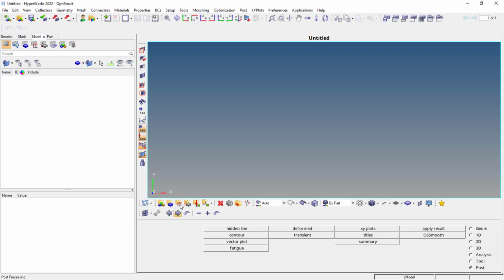Once you are done with the components, we apply the materials. Practically we consider this as the first step, that is applying the material. Once you apply the material, we go with the properties definition. There we assign the solid type, whether it is shell or solid, or PSOLID or PSHELL, what the thickness is, everything. Even the material will be defined for the particular property here.